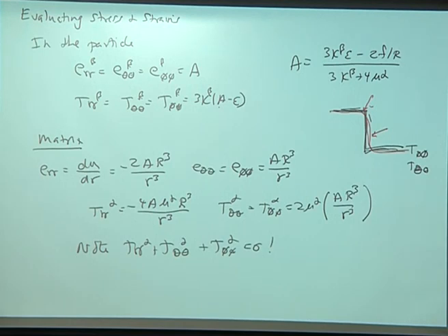The other thing I want to point out is if you look at the stress in the matrix phase and let F be equal to 0, it depends upon the sign of epsilon. Whether the radial stress is positive or negative depends upon whether epsilon is positive or negative. So it captures a lot of the basic physics and ideas of what's going on in the stress problem for particles. And now you've done the case where you have very small particles, so you can go back and claim that you're doing nanomaterials if you wanted to keep your sponsors happy.